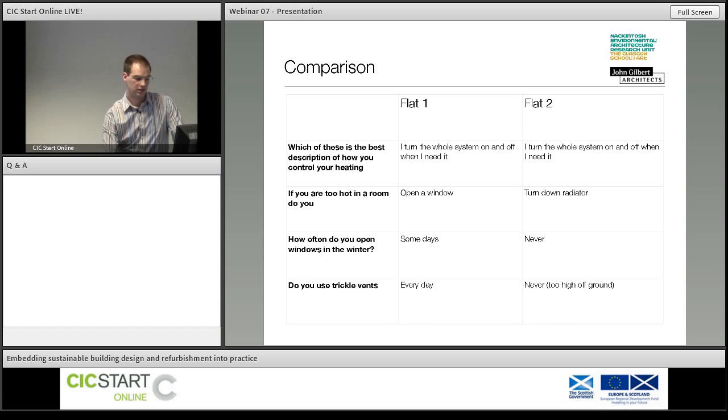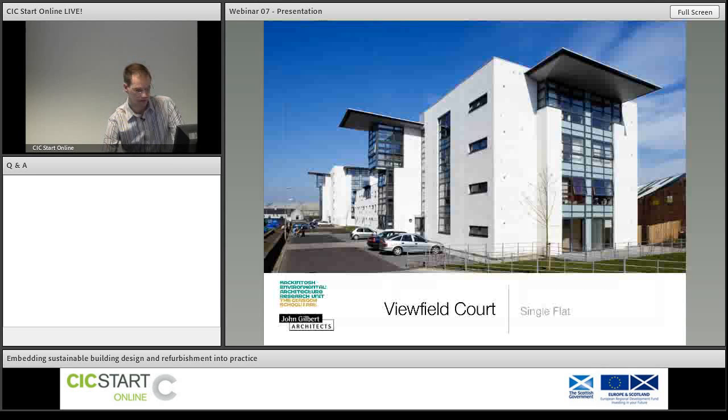Yeah, higher temperature leading to higher fuel bills. I think it's fair to say that actually the SAP on these houses was particularly low compared to the others for the floor area, and we think that there's solar panels on these, and that's obviously making a big difference. But the kilowatt hours is still high. You know, the actual energy use compared to the predicted use, there's still a difference. I think that's a fair point.